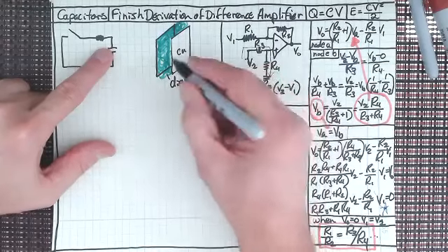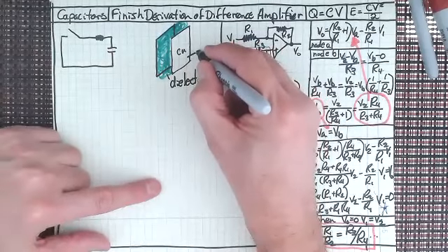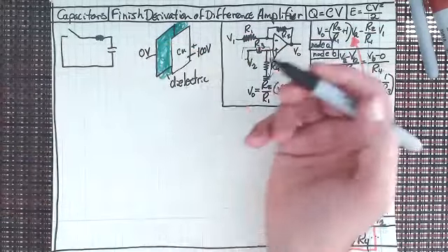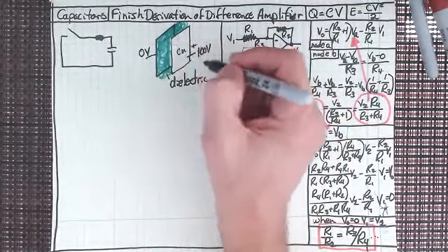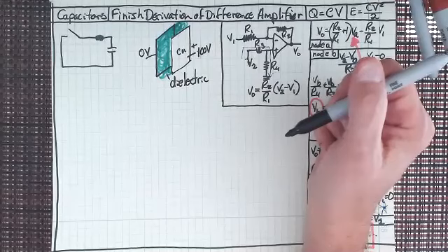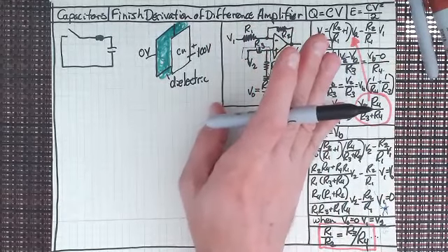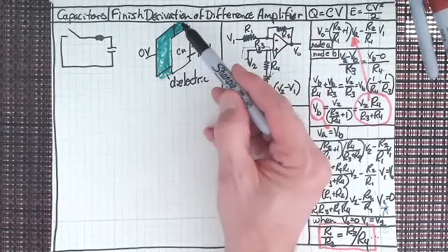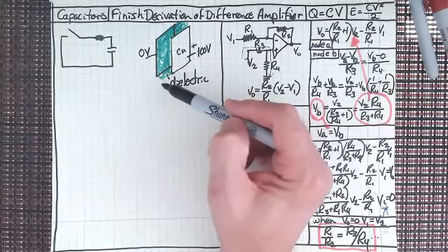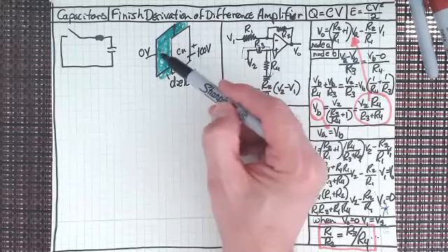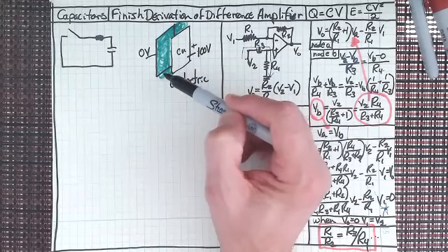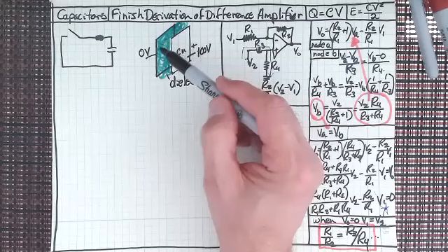And why do we put a dielectric in between the two plates? Let's say that this is at, I don't know, plus 100 volts, right? And then the other side over here is at 0 volts, connected to ground or whatever. So I've got 100 volts across there, don't I? And I've got this dielectric in here. And what does the dielectric do? Not all insulators are dielectrics, by the way. But the dielectric is a material, could be mica, could be barium strontium titanate, could be glass, could be air. There's a whole bunch. Could be epoxy, right? We could be looking at a microstrip transmission line across a printed circuit board, right? So there's a lot of things that we could look at for the electrical field.